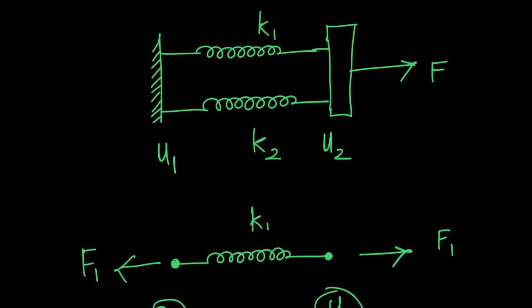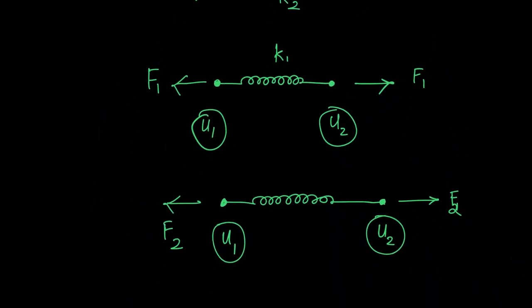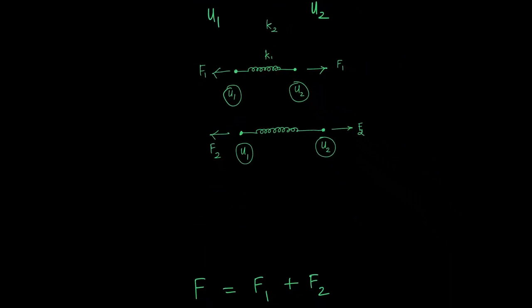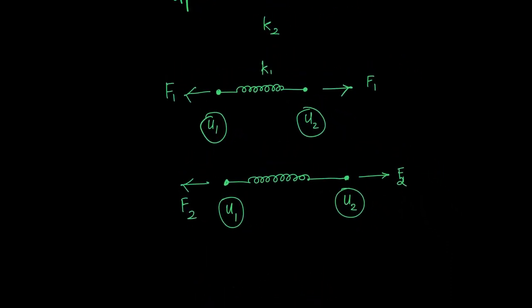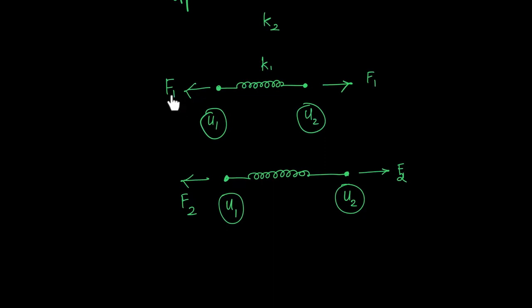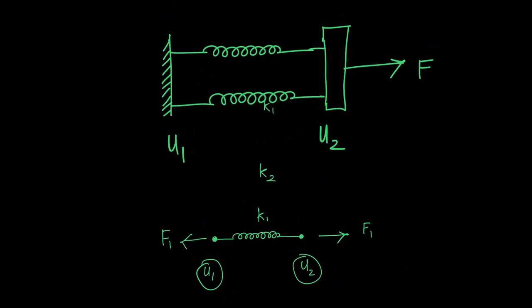For that, again we are starting with writing down the free body diagram of the spring. Here I have shown you this free body diagram of the two springs. As you can see here, the forces acting in the springs are no longer the same. But what is the same? The net deflection is same, but no longer the forces are same. So let's say the force acting in the spring 1 is F1 and the force acting in the spring 2 is F2.